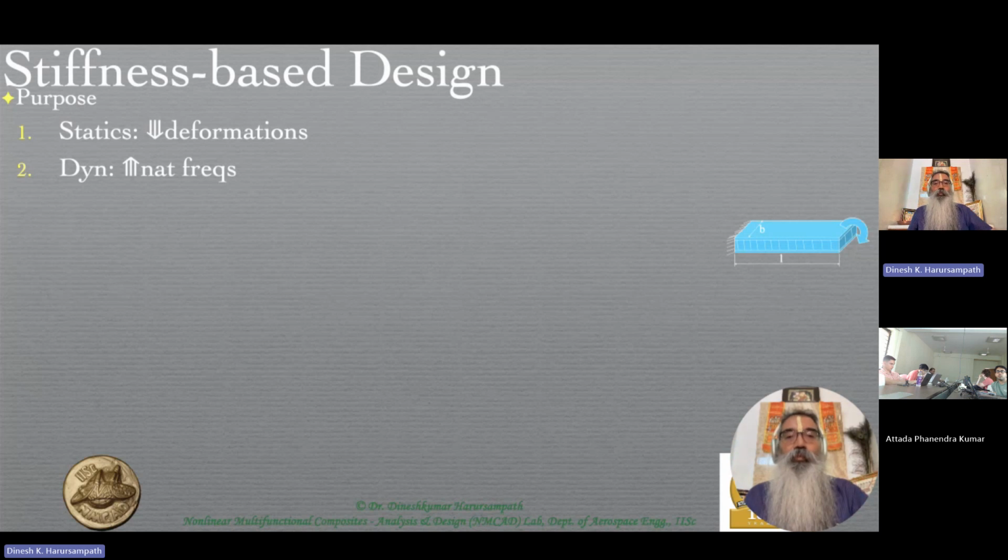So now our focus is not on torsion. Our focus is not on extension like in the previous slide. On this slide, we are focusing on a tip bending moment. In reality, you'd have a bending moment distribution throughout the span or semi-span, and then you'll have to take that into account in an appropriate way. But the end result, as far as the material property of concern for us, will continue to be the same. So we might as well, for this undergrad course, take a simpler geometry like what we are talking about.